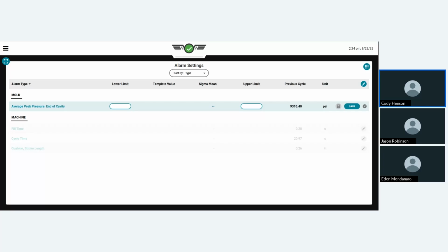So in this example, I'll say that I ran that and I got a short shot at 8,500 PSI. So I raised it to 8,800 to where I got sinks. So I would say my lower limit is 8,800. I know if I have above that, I have a full packed out part. There and below, I start to have sinks, and I don't want sinks, let alone shorts, to reach my operator. I want those to get additional inspection in case. So that is the lower limit.